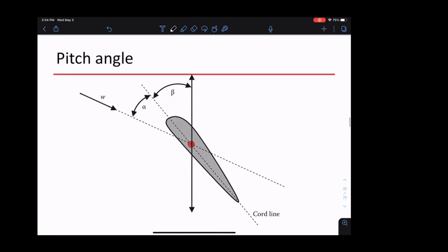So most of the time we think of controlling the blade as controlling the pitch angle, where the angle is just the angle the vertical axis makes. The center core line going through the turbine and the vertical axis make the angle called beta. By changing beta, we're indirectly changing alpha.